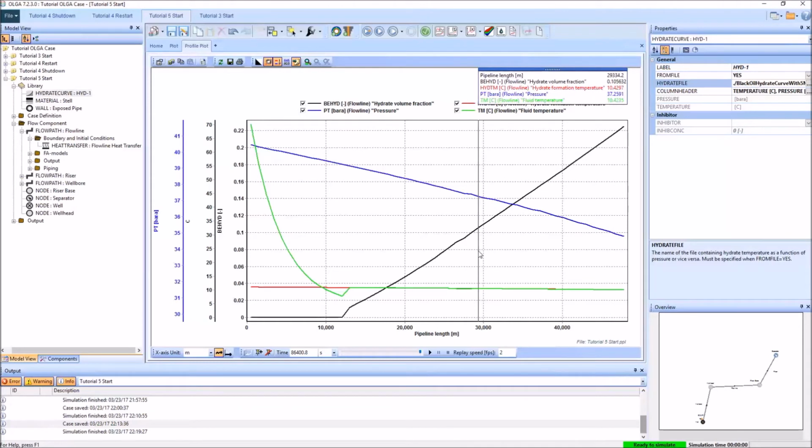Now what you should notice is that we actually do have less hydrate formation overall in this system. In fact, we have 22% at the end of the flow line, as opposed to the 35% that we had in the completely uninhibited case. And what this tells us is that because we have added some sort of THI to the system, the kinetic driving force for hydrate formation has actually been reduced.